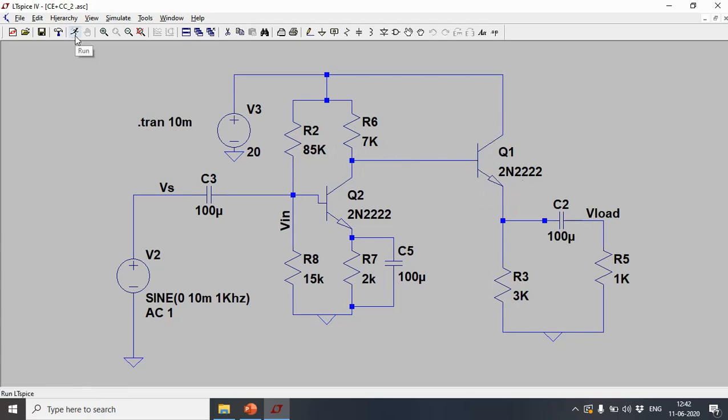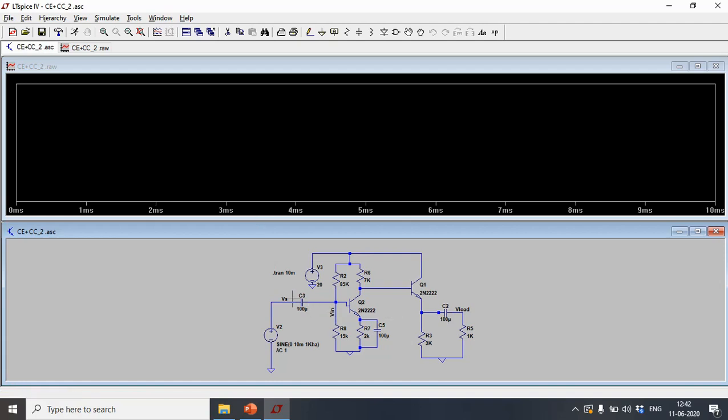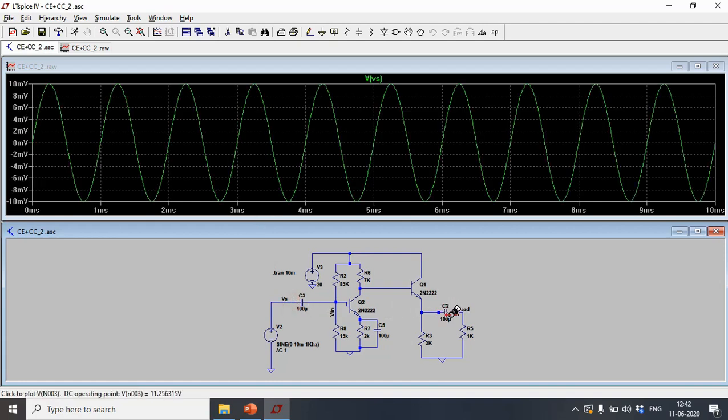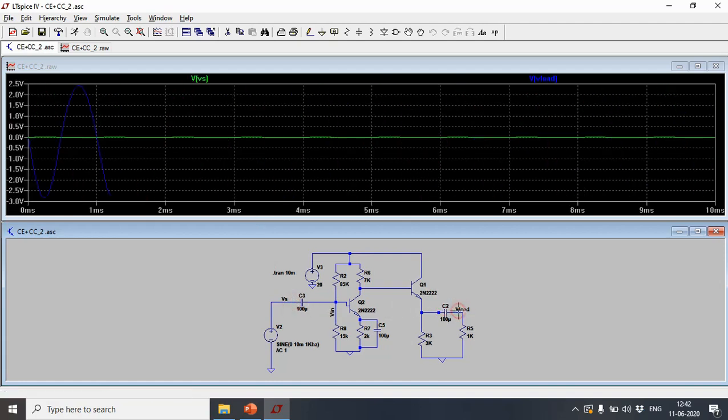So I can run a simulation and see what happens. See, you are still able to get a high gain. Those two resistances and one capacitance have been avoided, and we have coupled it directly out here, right? So this has simplified the circuit.